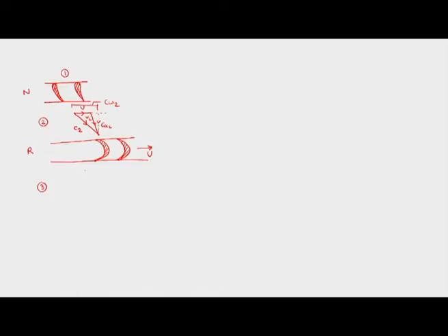At the outlet also we have the same u in the same direction, and then we have the relative velocity first, which comes out for the flow, and we have the absolute velocity. So this is V3 and this is C3. This is how our velocity triangle would look.